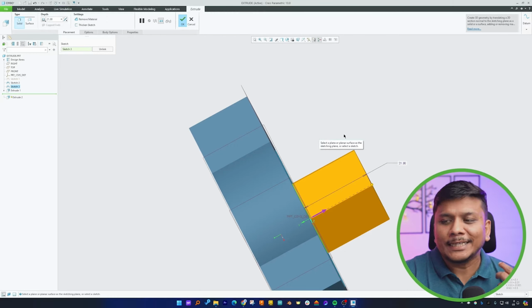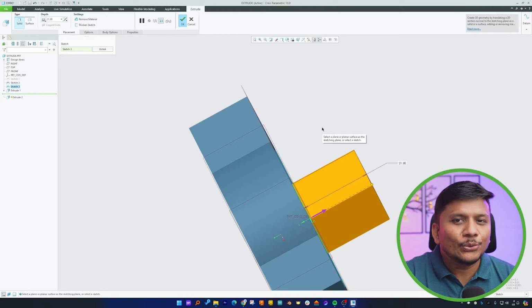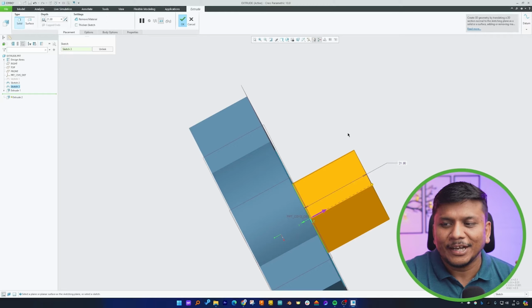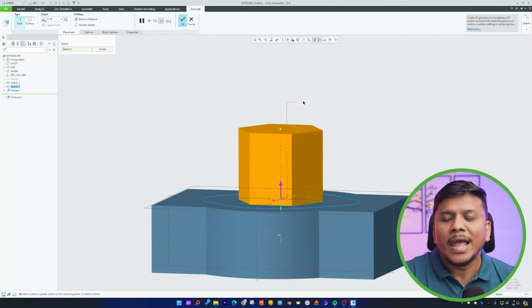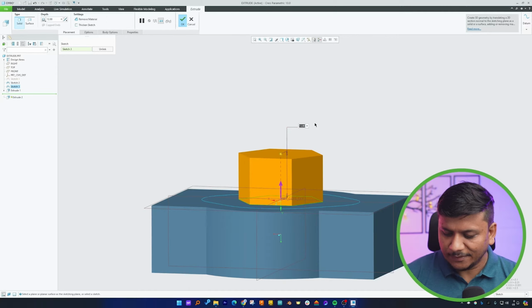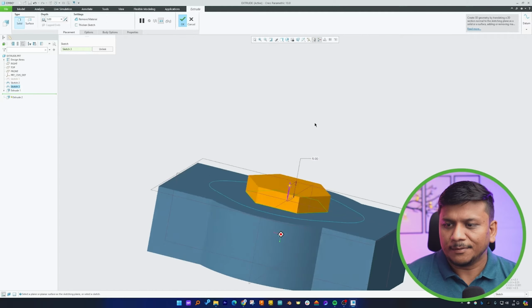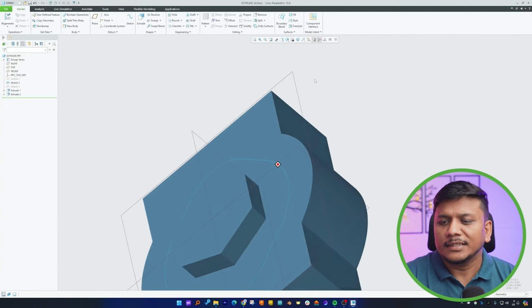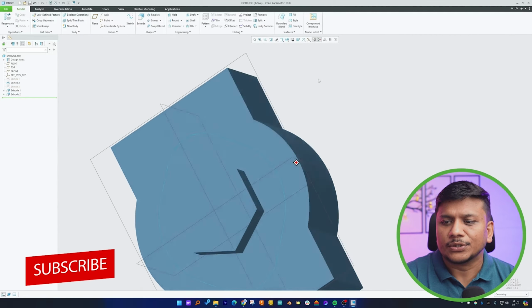And I would say it is really smart because the tool saw that this side is just 3D space. We do not have any object here, and then it got converted to addition of material. Okay, so now I can again specify the value. So let me put 5 here, and in this way, guys, we can make this extrude.